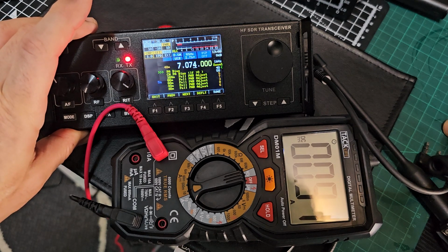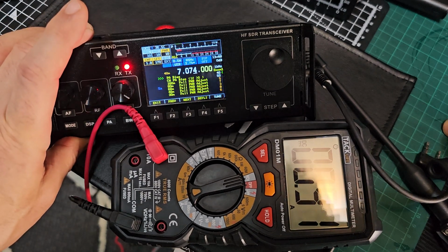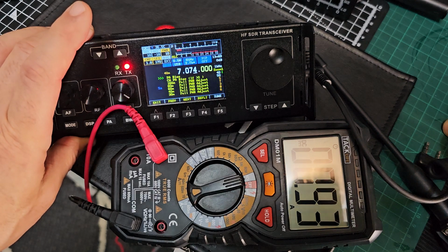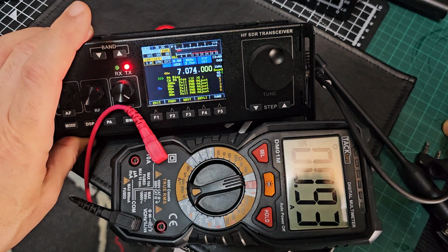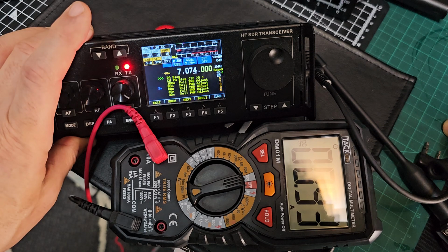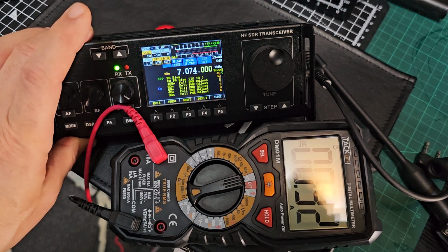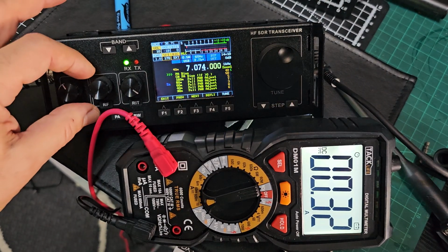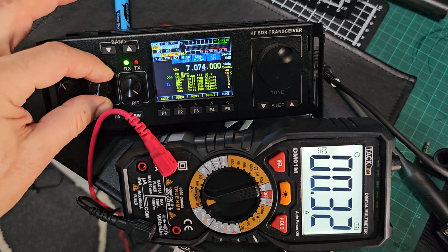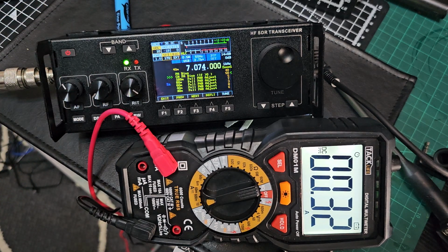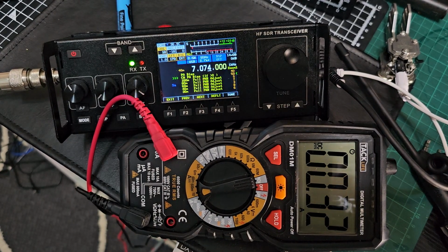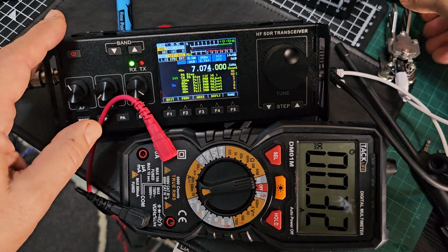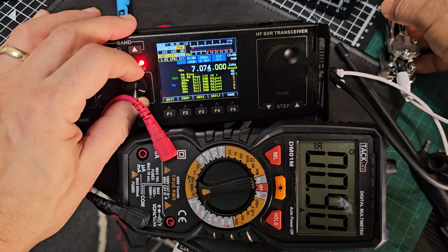So hopefully that's set well. Let me know if it's not, but I've watched some videos from N5ID and from Chuck, and this is the impression I'm getting of how you do this. So now I'm going to go down to the CW one. Okay, I'm going to grab my CW key. CW key's in. So now when we're transmitting, we're going to turn the bias to 0 again.